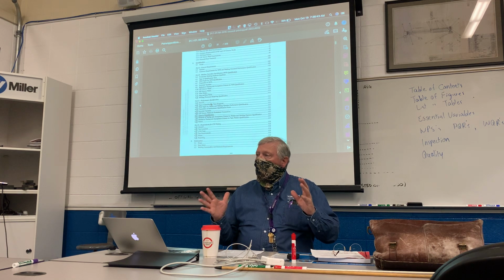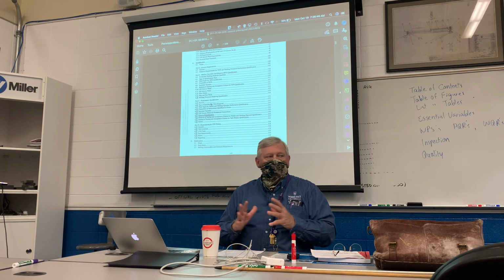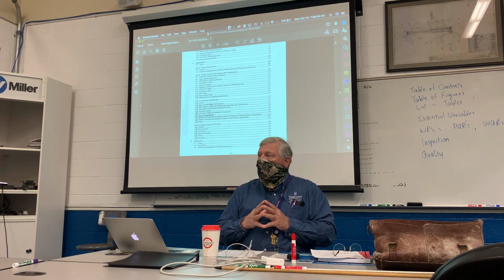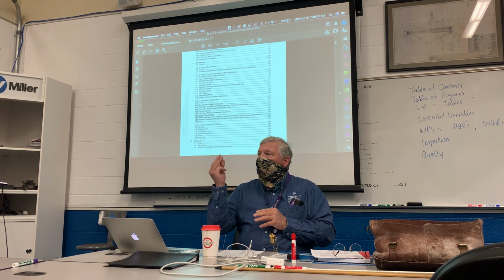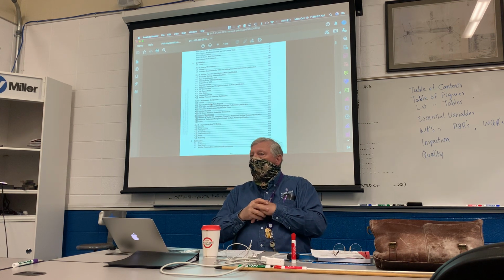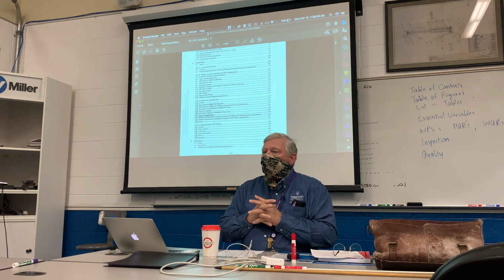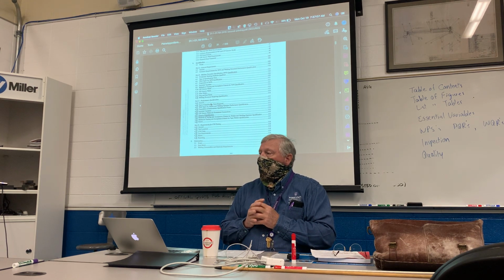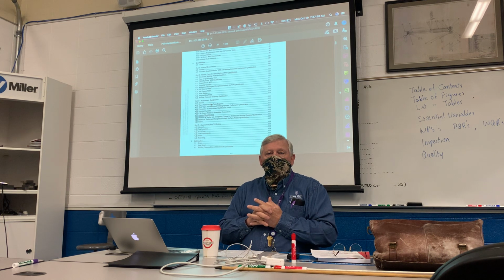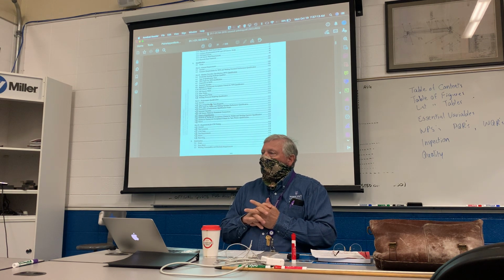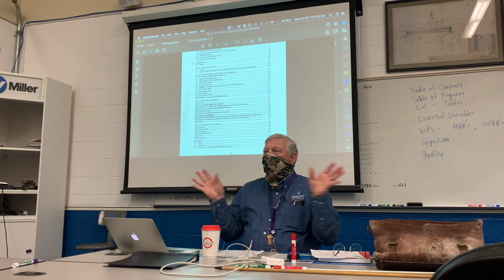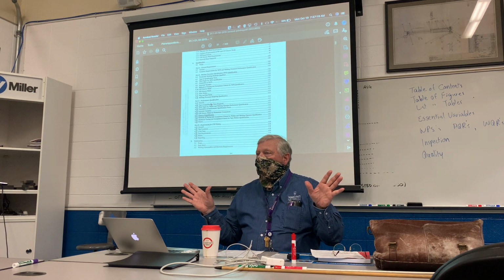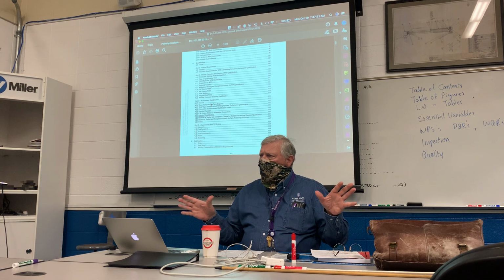Now, why would you want to use a pre-qualified procedure if you could? Makes your job simple. Makes it simple and cheaper. You can purchase one of those pre-qualified procedures at the end of ASME in Appendix E, and they cost about $200. And I actually have one that I can show you because I've purchased a couple of them. But that's kind of one of the differences. In API, there are no pre-qualified procedures. You have to qualify every procedure, even though it's the same thing every single time.